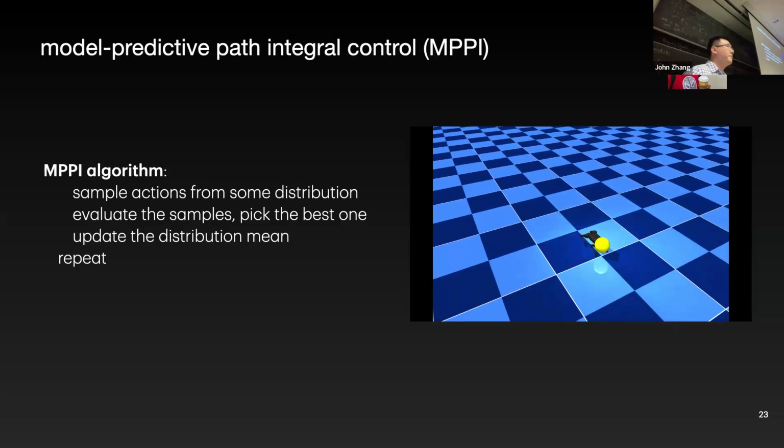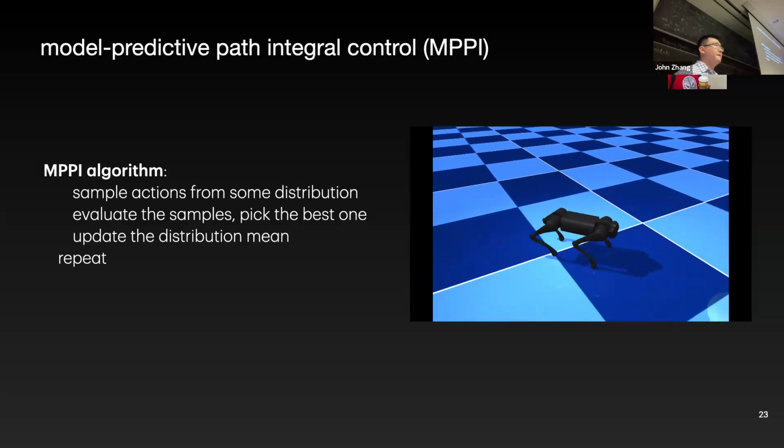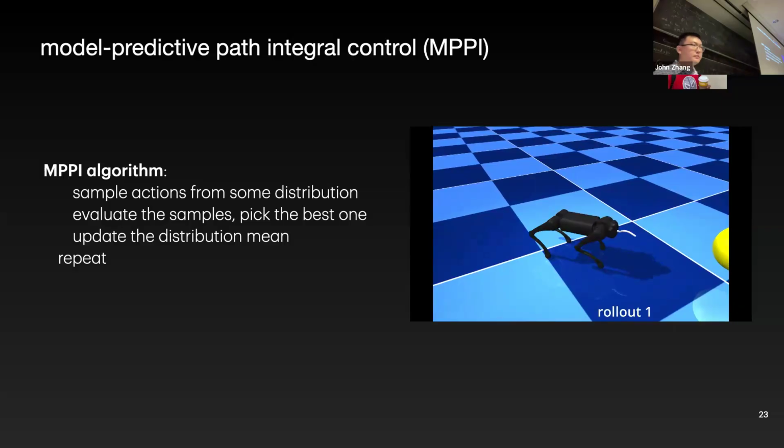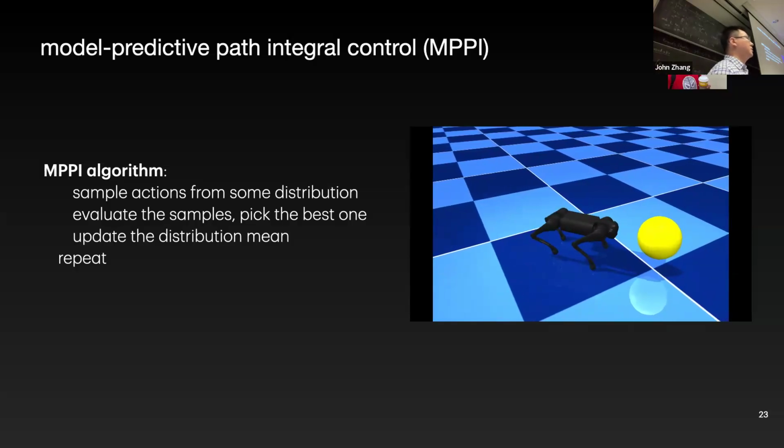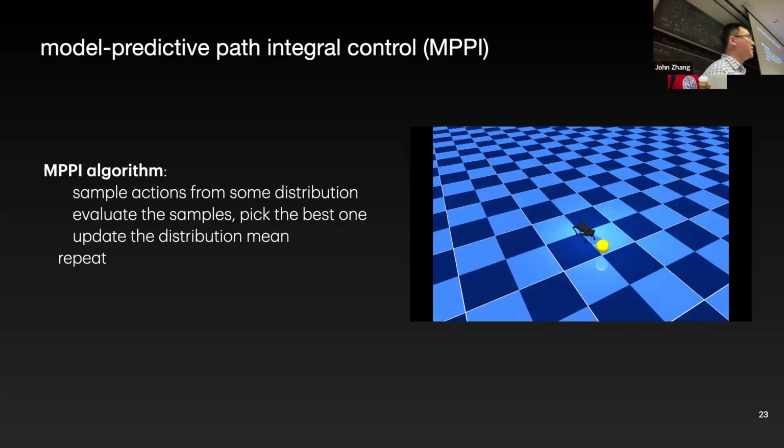Is that still using a similar model to what we were talking about with the Cheetah robot, like a point mass? Yeah, that's a really good question. Here we're not. It turns out computers today and simulators are fast enough that we're not doing model simplifications at all. We're just rolling out the whole MuJoCo nonlinear whole-body model, and it runs in real time.